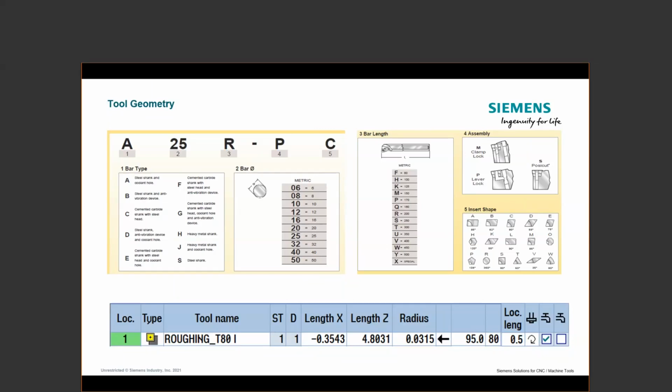So if I have a boring bar, maybe it's got a 5/8 shank. Well, that doesn't mean that the minimum bore is 5/8. It's probably something larger than that, because the cutting edge is always offset from that. So maybe the minimum bore is 3/4 inch diameter. Well, if I've got a 3/4 inch minimum boring bar and I try to put it in a 5/8 hole, I'm going to catch the back side of that boring bar with the back side of the hole. So that's where the minimum bore size comes into play. So that's a piece of information you're certainly going to want to know. However, you don't have to put it in our description at this point.